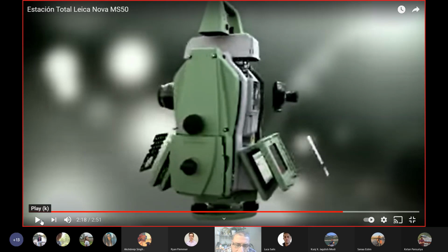With your hands, you can rotate the whole thing left and right, and also rotate the telescope up and down until you create what we call the line of sight. This motorized total station has a servo motor. The servo motor allows it to control the total station, where on the screen you can simply mark one area of interest, not a specific point, an area of interest.